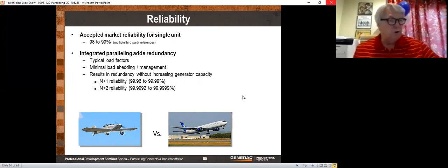They went out for a quote on a 2 megawatt generator, and we quoted that, but we offered them an alternative for 5 parallel generators, 500 kilowatts apiece. And we got an order right away, which is not typical. I think that's maybe the only project I can ever remember where I got an order that fast. Turns out they thought we had made a pricing mistake, and they wanted to hurry and get us to accept the order before we figured out that we had underpriced it. Well, we didn't underprice it. 4 500 kilowatt generators is significantly less expensive than a 2 megawatt. It's easier to install. It's easier to maintain. It is easier to get parts for. It's easier to troubleshoot. And it turns out that with those, the actual load on the plant when we had our first outage was about 900 kilowatts.